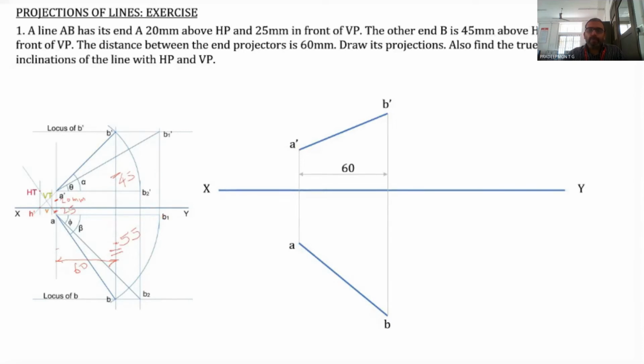So the front view length as well as the top view length need not be marked on your drawing. Now we draw a line from A dash. This is the angle alpha, which we don't need to mark. And here the beta is also marked. Now we rotate AB. This AB1, the point B1, is to be found out.